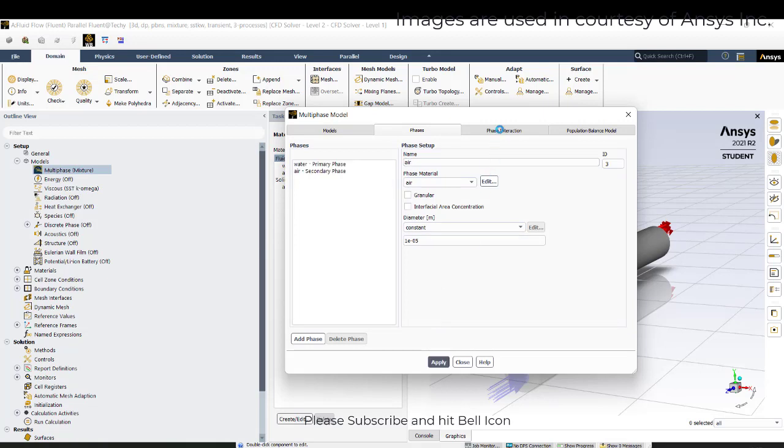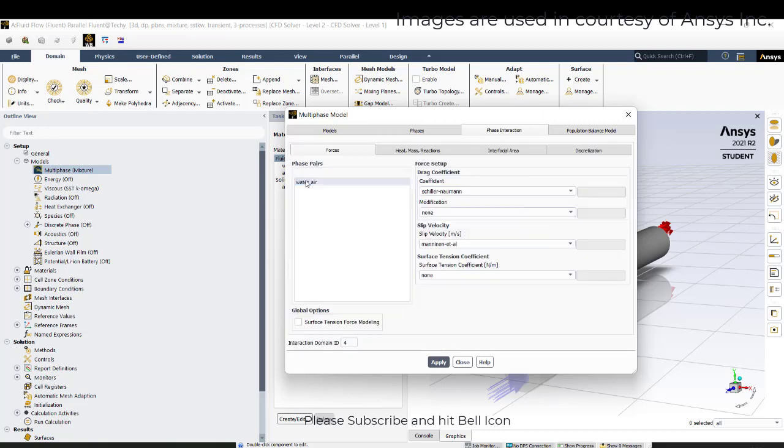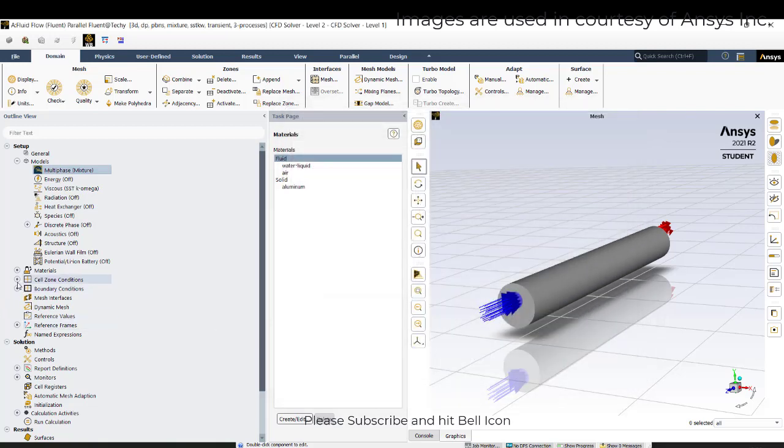Apply. Now in the phase interaction, there is a slip velocity between air and water, which is given by the Manninen equation. There's also a drag coefficient given by the Schiller-Naumann coefficient. I'll leave the remaining settings at default.